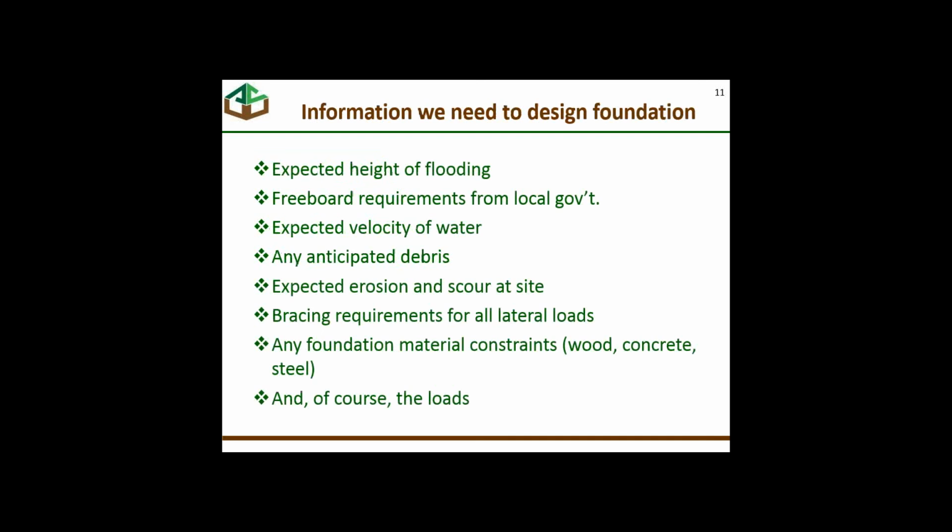The information that we need to design a foundation includes these bullets, and you might think of one or two other pieces of information that would be helpful. Certainly the first is how high do we think the flooding is going to be? Is the flooding in what FEMA calls a velocity zone where we get waves, or is the flooding in more of a riverine area where we would expect water to rise and then fall, but not come with very many waves? So it just depends on the kind of flooding that we get as to how we're going to proceed with the design. But the depth of flooding is an extremely important starting point.